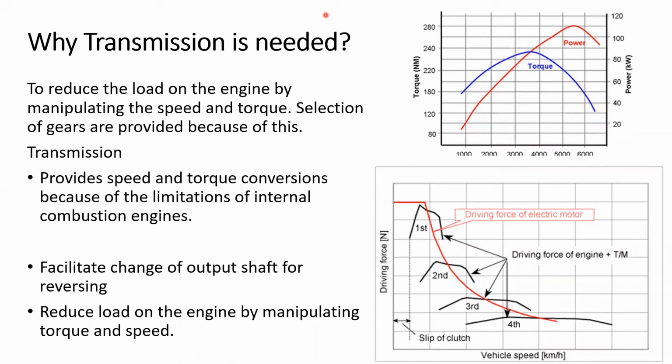In such a case, the vehicle will not be able to move, because that much tractive effort means we go over the static friction area, so we don't have any traction afterward. The wheels will start to spin.